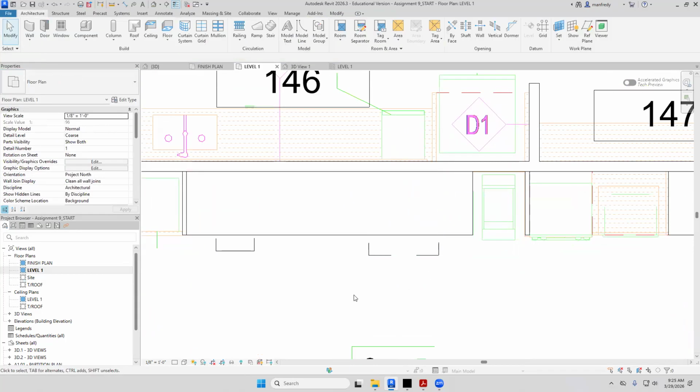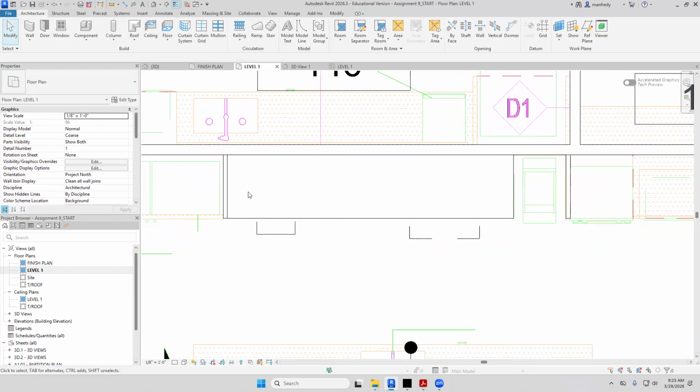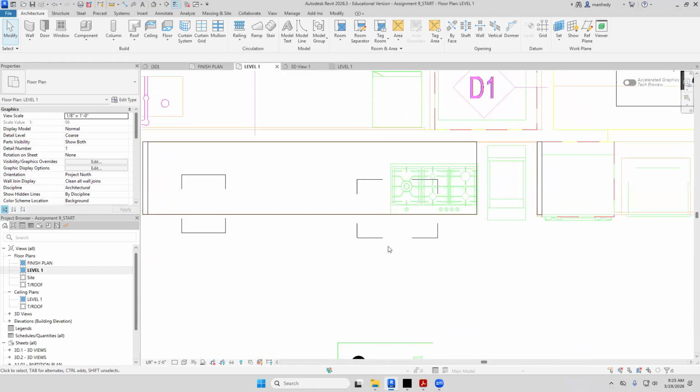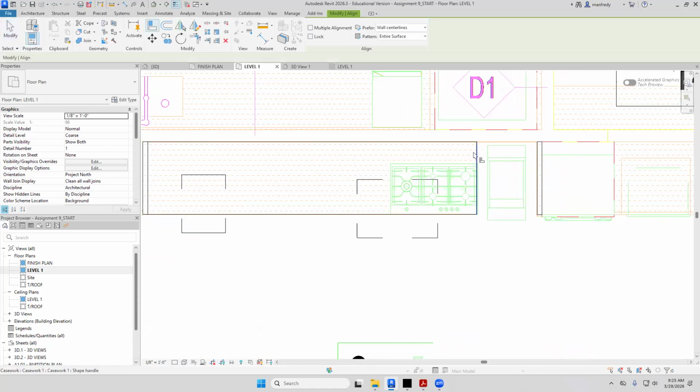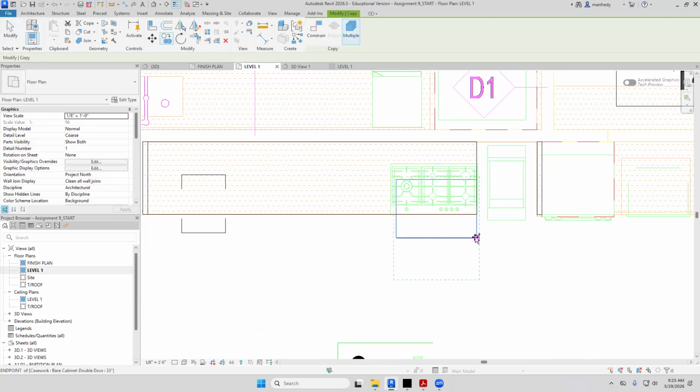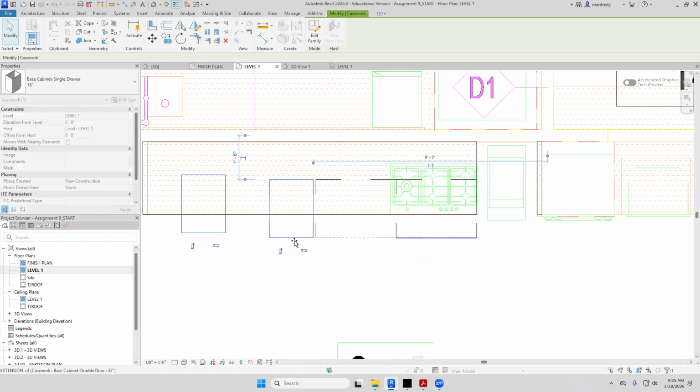There. And when you put these in Revit, they'll go underneath the countertop, which is why they're showing dashed. And you might want to make this view wireframe so you can see underneath the cabinet. But there it is. And I'll simply line it up with the edge of the countertop here and take this one and duplicate it. And then I'll grab this one and move it over.